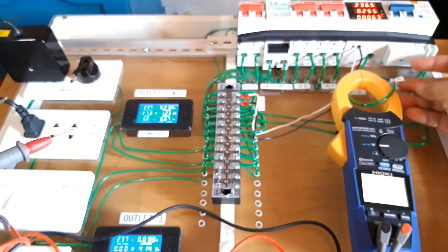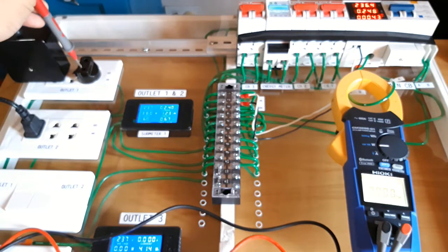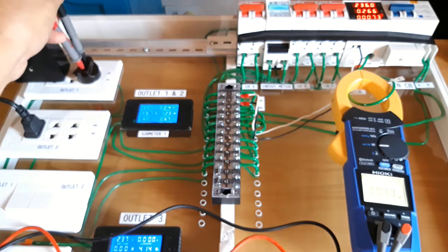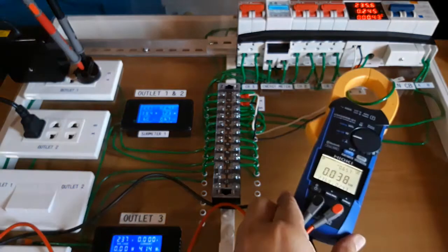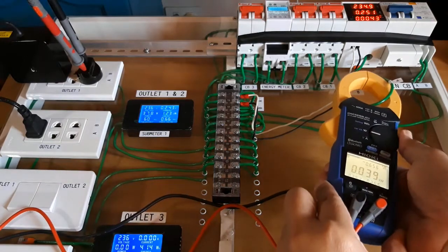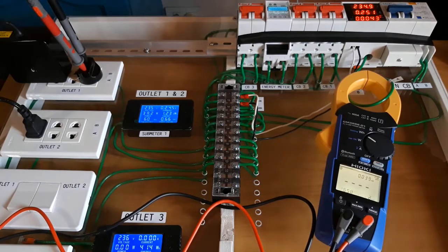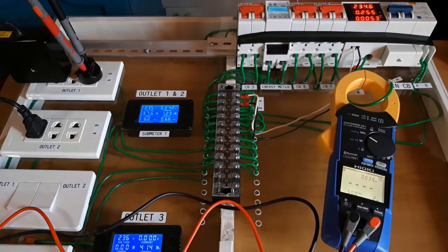And since the line being clamped is line A, therefore the red probe must also be connected to line A for voltage monitoring, which in this case is the lower part of the outlet, and that will give us a correct power measurement. The same goes for energy measurement, which is an integration of 4 different values at the same time: voltage, current, power factor, and now time. So it also requires the correct orientation of the current clamp and the voltage probe.